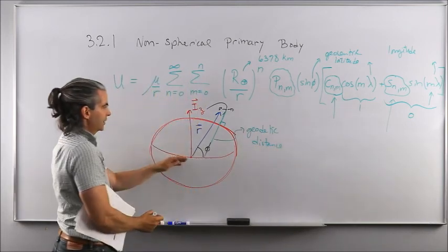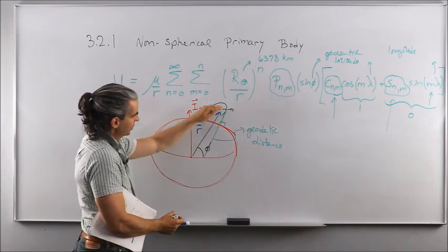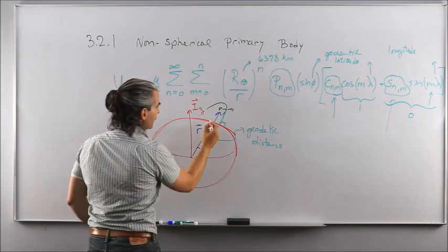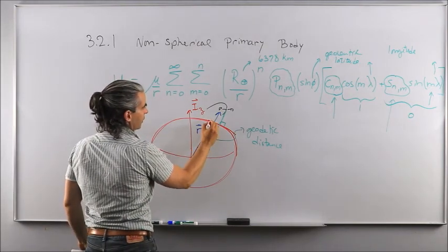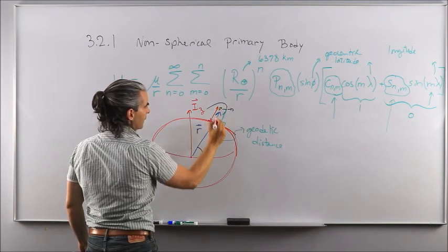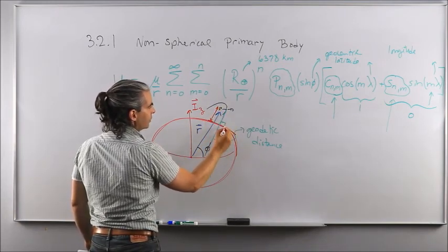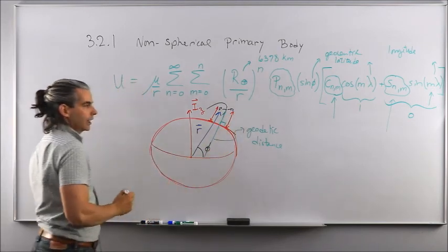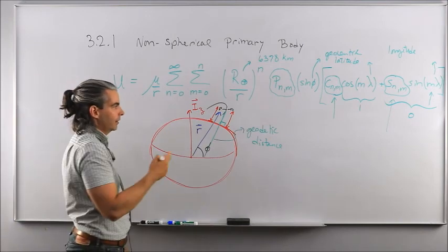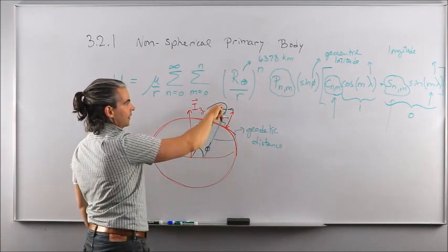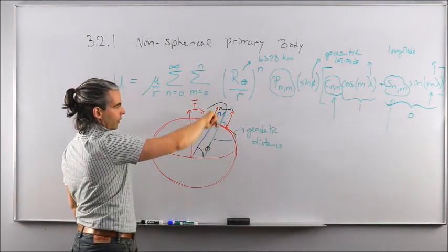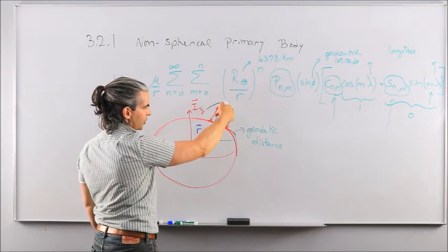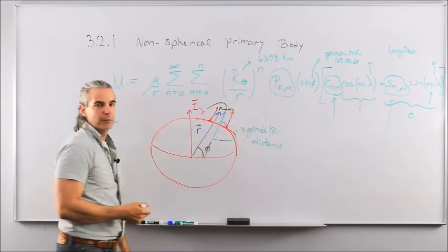And related to geocentric distance and geodetic distance, there are also geocentric altitude from the surface of the Earth here all the way to the spacecraft along the blue line, and the geodetic altitude from the surface of the Earth to the spacecraft but along the green line. Okay, so don't confuse the two, especially when we talk about altitude. Geocentric altitude is following our good old position vector, whereas geodetic altitude is measured perpendicular to the ground below the spacecraft.